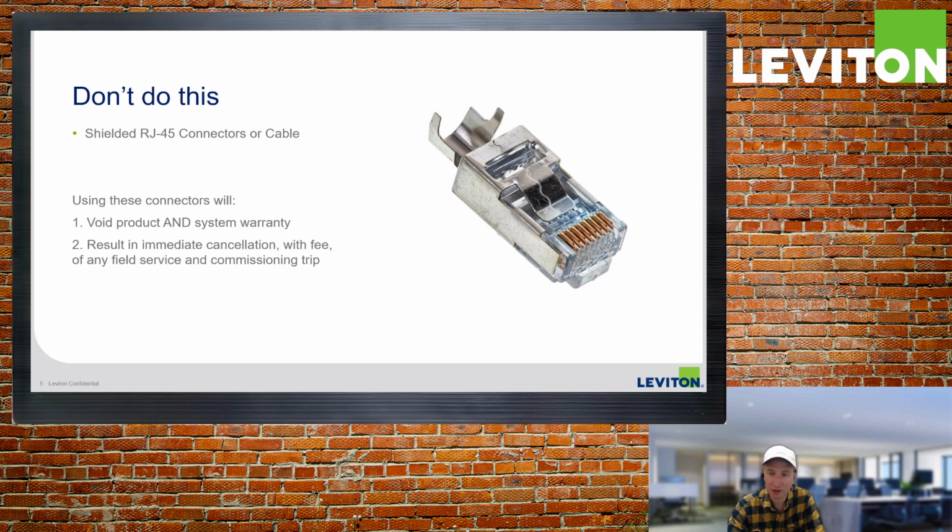It doesn't require them. It does not improve anything. In fact, just the opposite. It makes it so that your system will not work reliably, and in many cases, not at all. If we find shielded RJ45 connectors or cables on your job, it will void the product and system warranty.